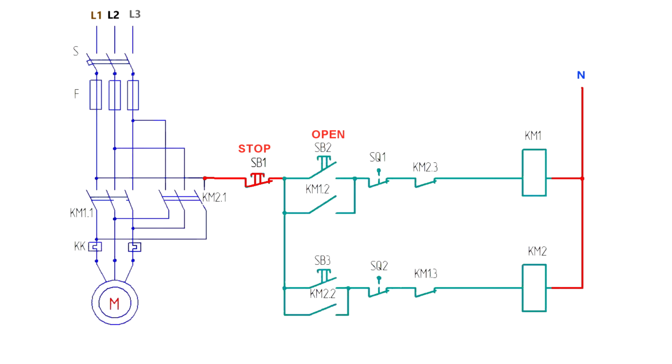To prevent this from happening, there is a self-locking contact in the circuit. The self-locking contact is one of the normally open contacts of the contactor contact group, which is connected in parallel with the open button. That is, when voltage came to the coil, all contacts closed, including the self-locking contact. And now the coil power has gone through this contact, bypassing the button. So the operator can safely release the button.